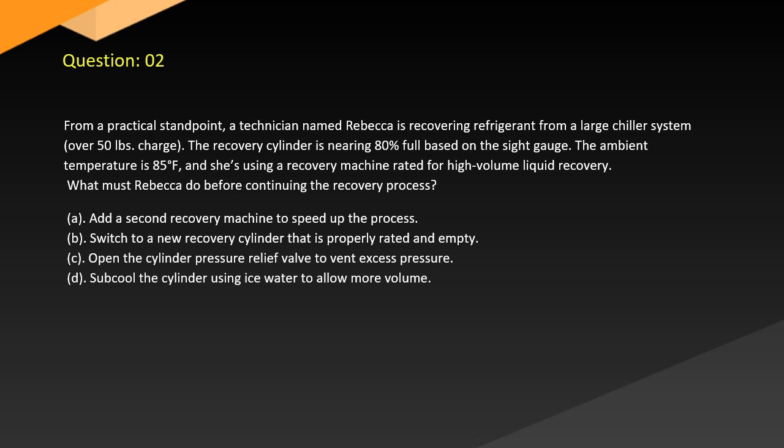Question 2. From a practical standpoint, a technician named Rebecca is recovering refrigerant from a large chiller system with over 50 pounds of charge. The recovery cylinder is nearing 80% full based on the site gauge. The ambient temperature is 85°F and she's using a recovery machine rated for high volume liquid recovery. What must Rebecca do before continuing the recovery process?